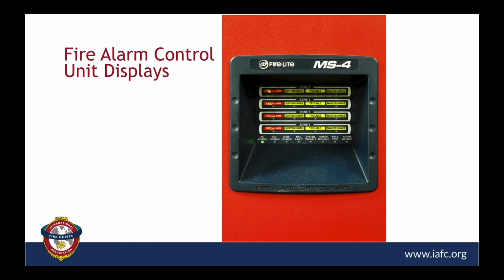But a zone here could have up to 30 devices on it in some cases. Generally, you try not to put more than one water flow switch on a zone, but if you're putting smoke detectors, pull stations, heat detectors, you can put multiple on a single zone, so you're not going to know where that fire is specifically, but you'll know what area or what zone of the building the fire is coming from.